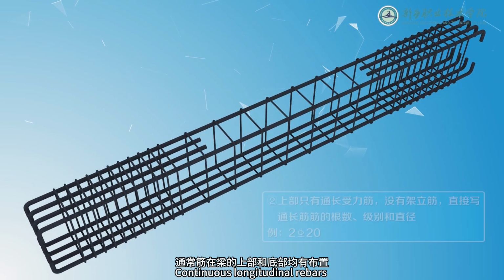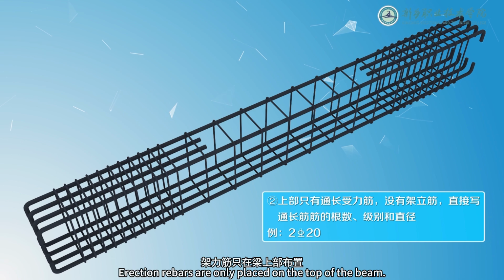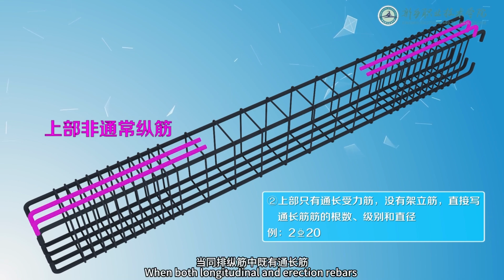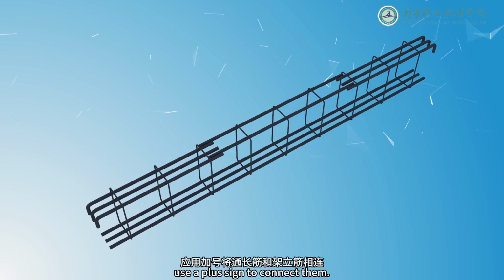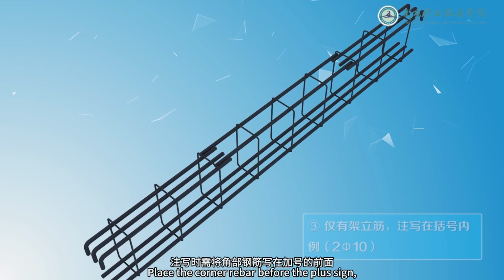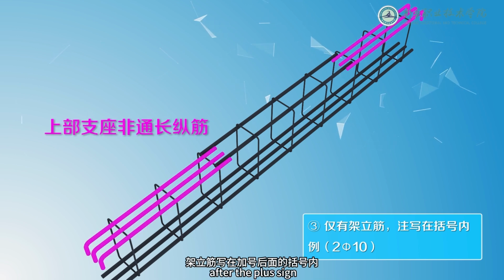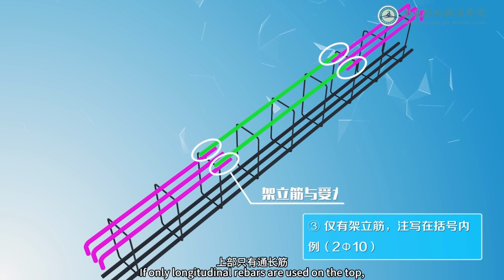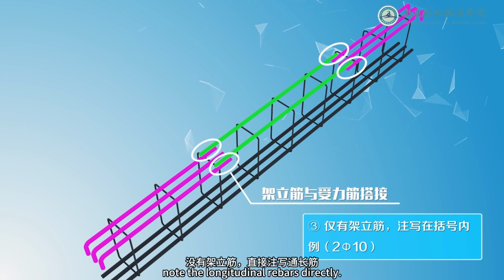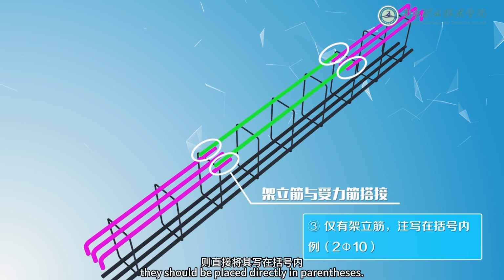Continuous longitudinal rebars are placed at both the top and bottom of the beam. Erection rebars are only placed on the top of the beam. When both longitudinal and erection rebars are in the same row, use a plus sign to connect them. Place the corner rebar before the plus sign, and the erection rebars in parentheses after the plus sign, to distinguish it from the longitudinal rebar. If only longitudinal rebars are used on the top, note the longitudinal rebars directly. If only erection rebars are used, they should be placed directly in parentheses.